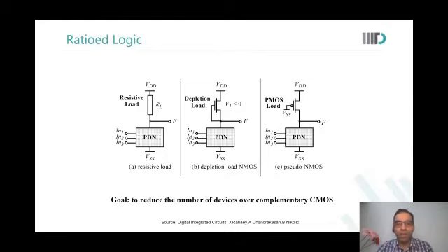Now, we just saw that by using these always-on loads, resistances and depletion loads, what is the challenge that we expect? That the output will not go to pure zero, because the PMOS is always on. Some current will come either from RL or the PMOS or the depletion load that we have put. Are you with me on this? Any questions still here? You can put a +1 in the chat window if you don't want to unmute and speak. I will not move forward until I get feedback.